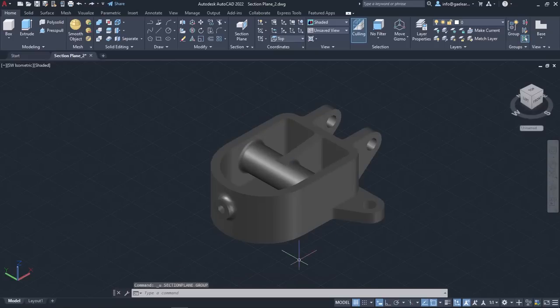At this point, I will show you the different types of sections that you can create. When you activate the Section Plane tool, apart from the Draw Section and the orthographic options, there is also a third option, which is the Type option. If you select this option, 4 types appear: plane, slice, boundary, and volume.